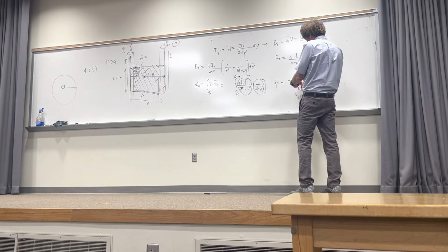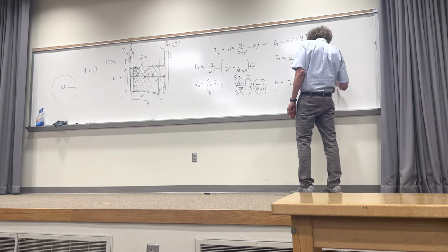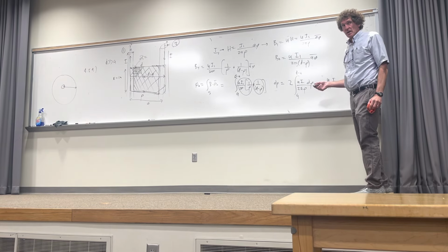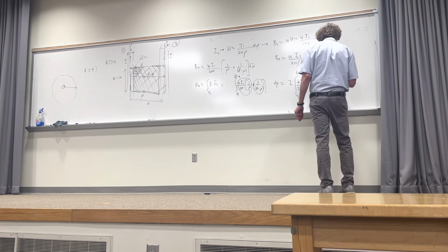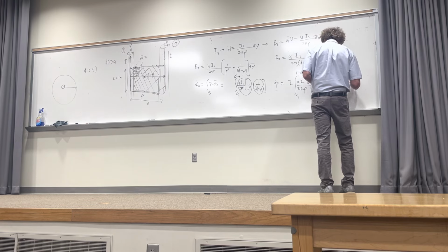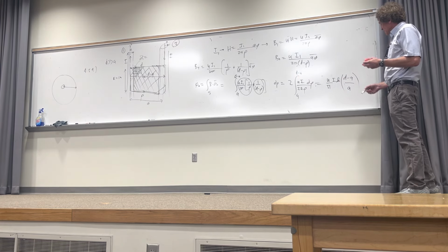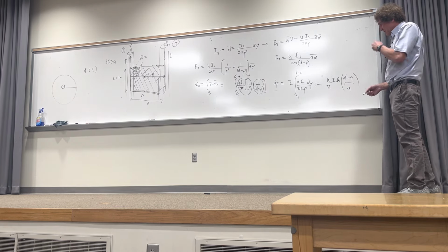I get 2 mu over 2 pi, so I get really mu over pi, right, I. And then the integral of d rho over rho is 1 over rho, natural log, right, natural log of d minus a over a. And if you want to, you could assume that this is basically d, or it could be d over a.